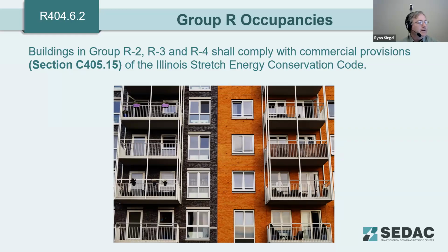And for cooking, for all electric, again, the range, it calls for a 40 amp circuit. That does fit most electric ranges will work with 40 amp. There are some out there that do require a 50 or larger. Again, this is not going to provide infinite options for future provisions, but we're trying to make it so that people do have options in the future.